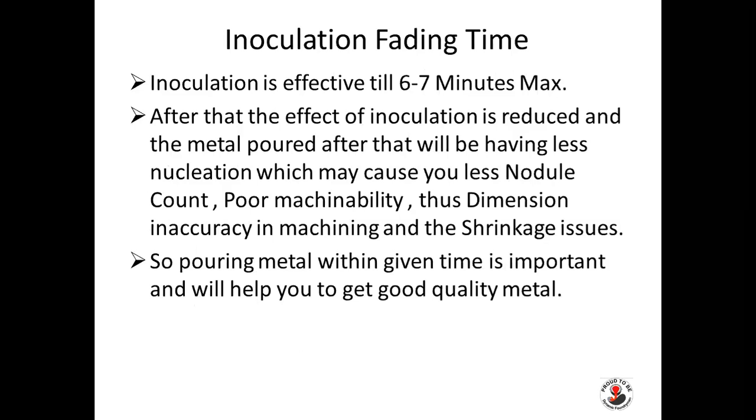Inoculation is effective till 6 to 7 minutes max. So fading time of inoculation is very important. You have to finish your pouring before that stipulated time.